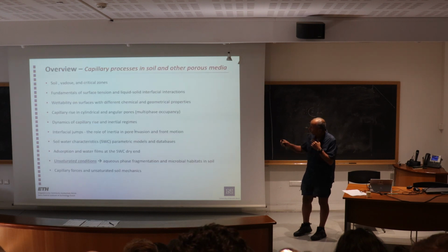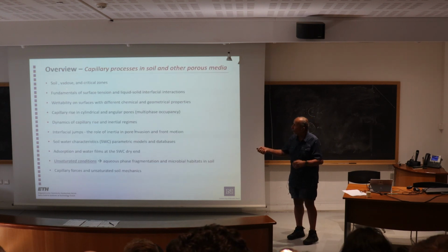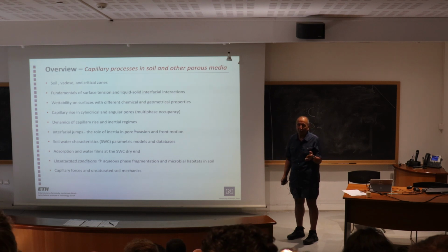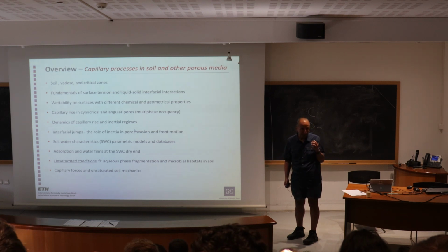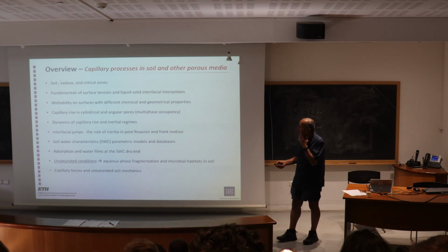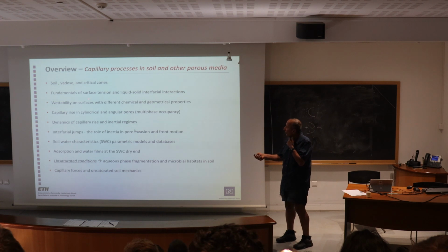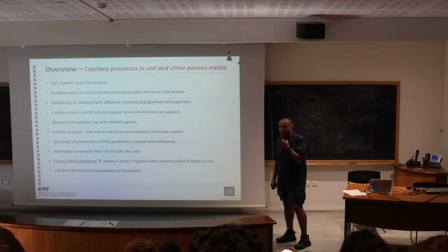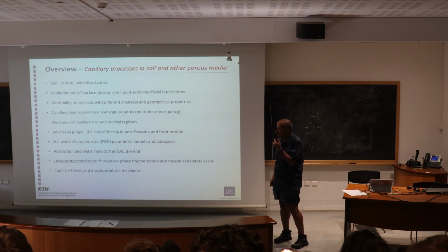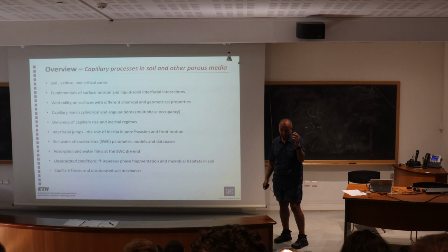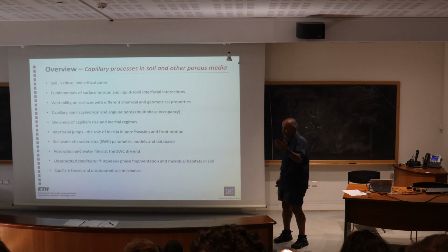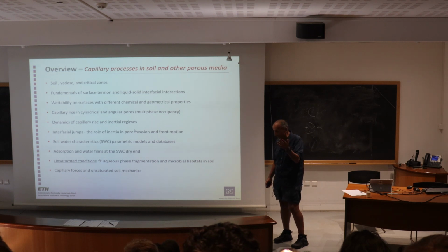So we'll talk about the domains. What is soil, vadose zone, and critical zone? I'll try and place those in context because we hear them and it's not always clear what that means. We'll talk about fundamentals of surface tension and liquid-solid interactions in soil and porous media in general, but I'll focus on soil. When I say porous media, I'm thinking soil, but of course, when Rene says porous media, he thinks fractured rock, and so these are all geologic porous media.